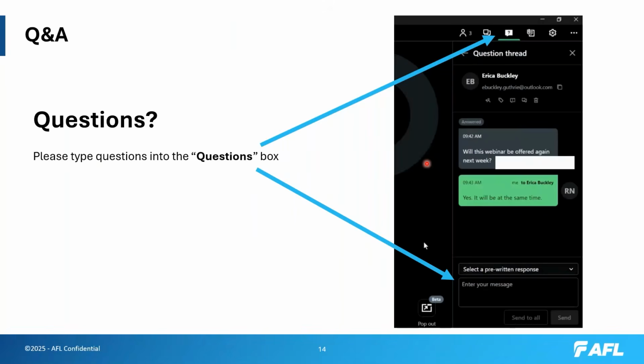So the first one, what we have here is how do we use our current 90R to do 16 fiber splicing? Pretty simple question. The first thing you have to ask yourself when you say 16 fiber is the ITU spec, what type of fiber are we dealing with? And secondly, what are the physical characteristics of that ribbon?